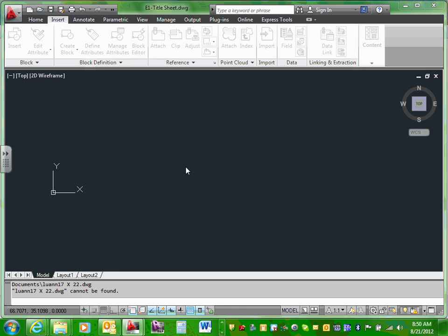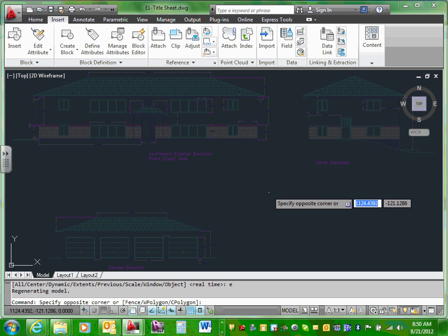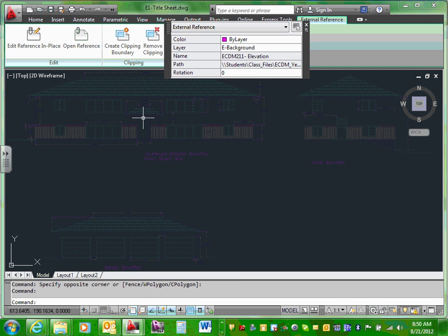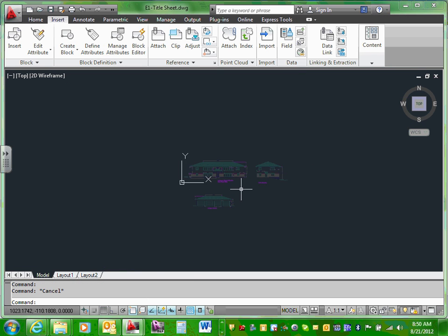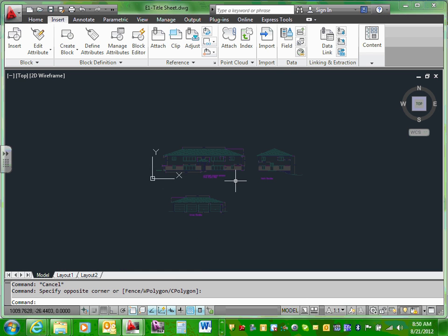and click. Okay. Now, do you see anything else? No. Now go hit Z, enter, E, enter. Z, enter, E, enter will zoom. That will zoom all. Do you guys see what you brought? Okay, you just brought these files in. And if you click on them, they're all Xref. You can't see them on mine. Can you? You can barely see them on ours. Yeah. You can barely see them on yours too.